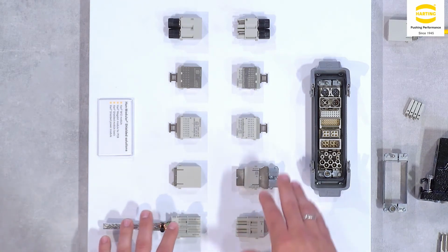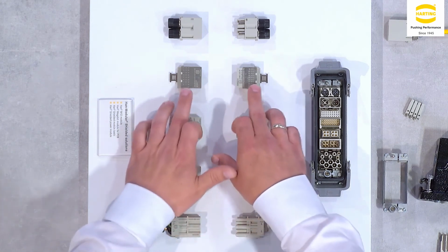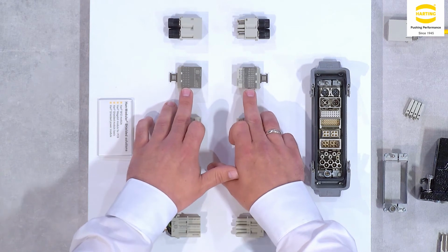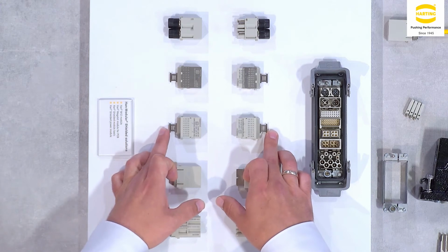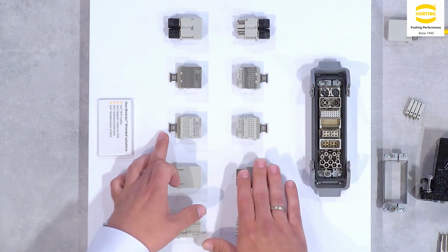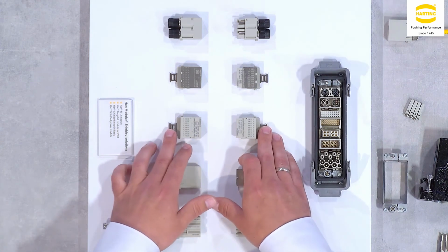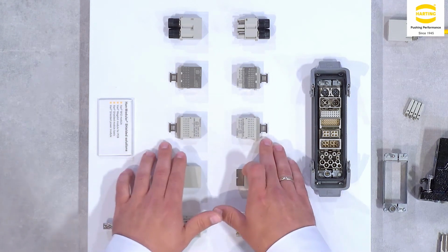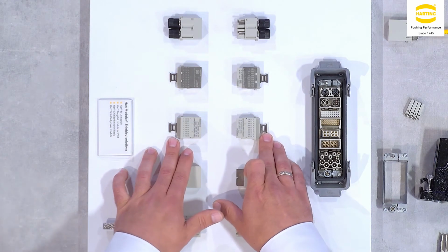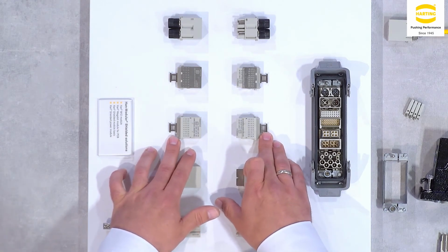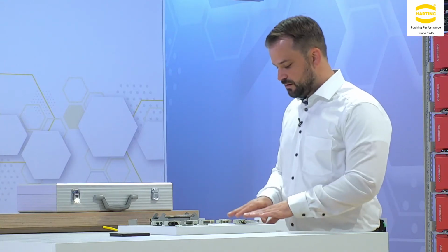Coming to the next module, the shielded basic light module, there we see that it is not implemented into a 360 metal cage anymore, but here we have a metal sheet that makes the connection within the industrial connector, and this metal sheet is responsible for bringing the shielding from the male to the female module. So also here we have the principle of attaching the shielding to the metal element in the rear, also with a zip tie.